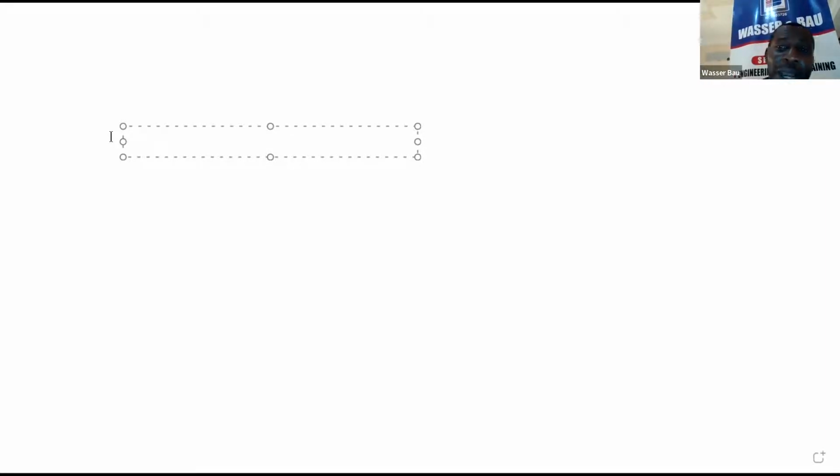If you are building a road now, I can tell you if the road has 2 side drains, the cost of asphalting and the cost of good drain is almost 50-50. I know sometimes it revolves around 60-40, but if you must do a good drain on 2 sides of the road, your drain will take almost 50% of your work.